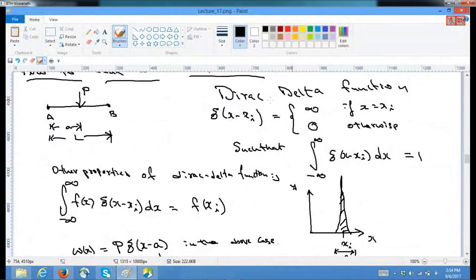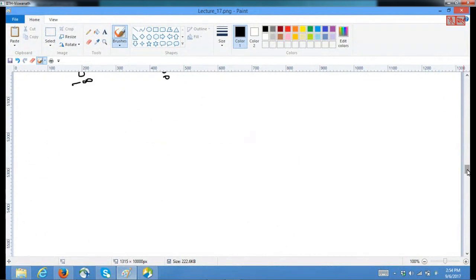So we can use this to handle our point loads, or we can come up with it in the same manner as we used for the previous boundary terms. But anyway, let's use this. So the integral of w(x) N transpose dx was our boundary term due to the distributed load.